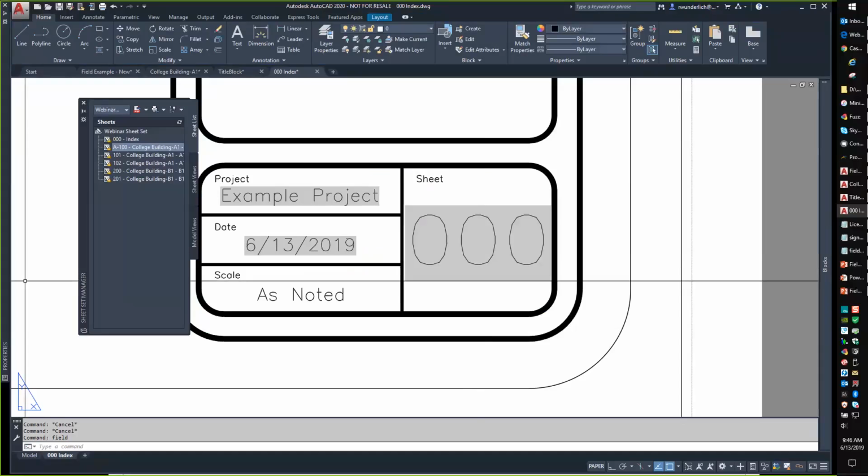Let's see, on a sheet that has several views, it is very tedious to drag in 20 views to create dynamic callout blocks. Would you advise dragging in pre-saved views from an XREF, or to XREF the drawings in model space and then create the views in model space? I would honestly probably advise preset views from an XREF, or you could XREF the drawings in model space, but you're still going to come in and have to create those 20 views in layout space.